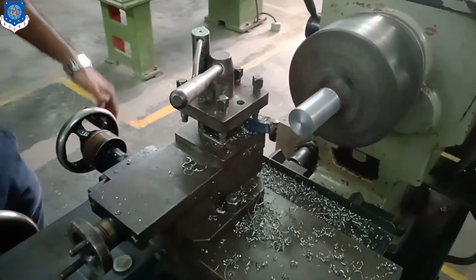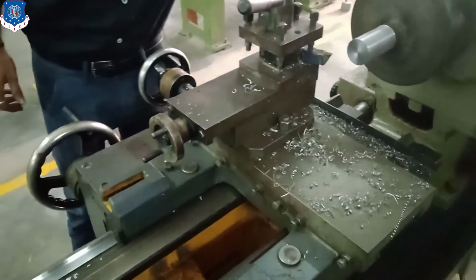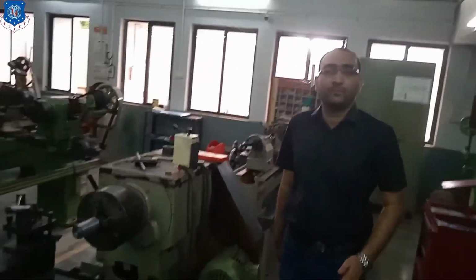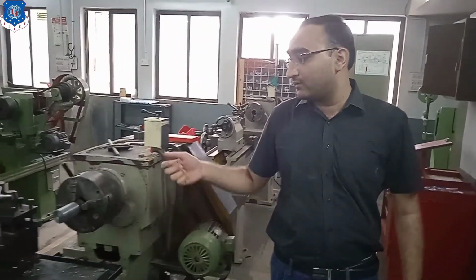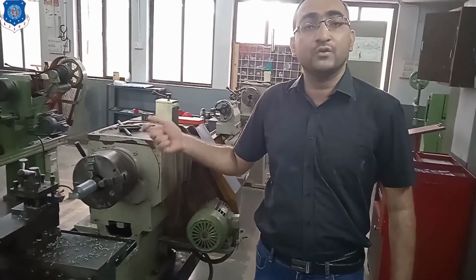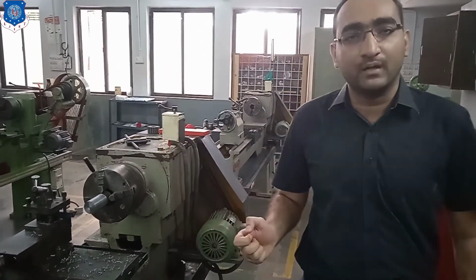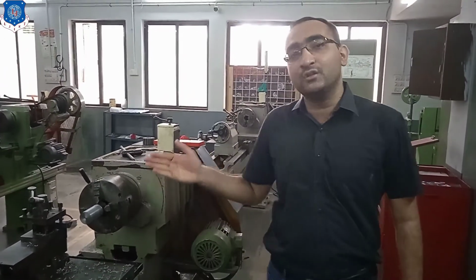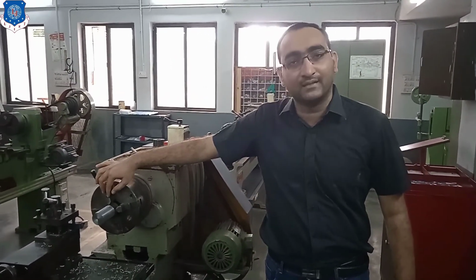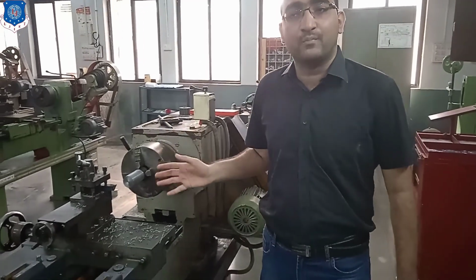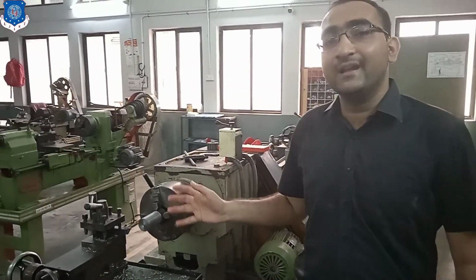As you can see, whenever your tool reaches towards the jaw, we have to stop our workpiece, because otherwise your tool will be in touch with your jaw, and it will definitely break. So that is the reason when you reach towards the jaws, at that particular point we have to stop our machine and take back our tool. And in this way you can see over here that the operation which is performed is known as a turning operation.